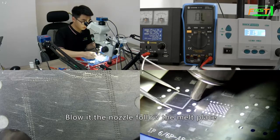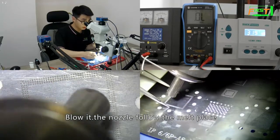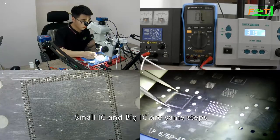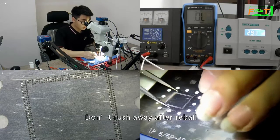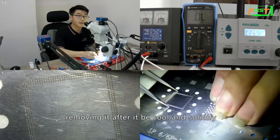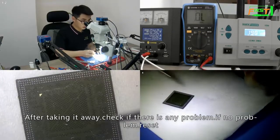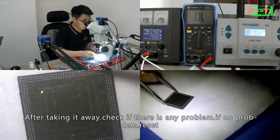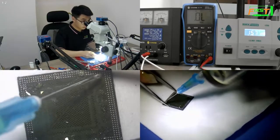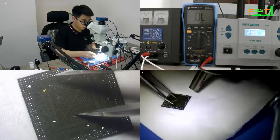Blow it. The nozzle follows the melt place. Small IC and big IC are the same steps. Don't rush away after reball, remove it after it is cool and solidified. After taking it away, check if there is any problem. If no problem, reset.